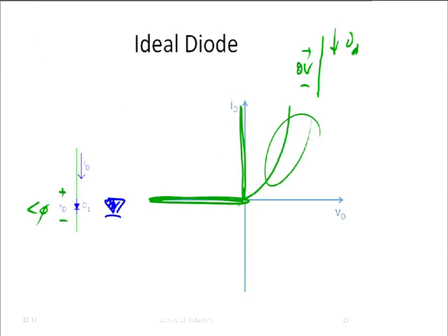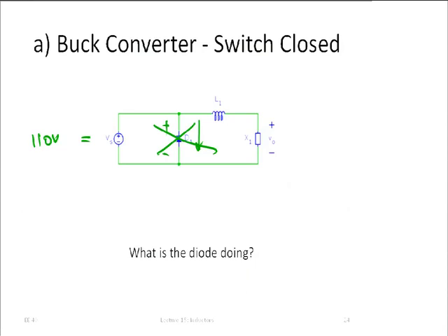Why does the current go that way? It's a passive element, so the current wants to flow in the direction of the voltage, and there's a diode there, and the diode says, stop. It's like a one-way street, right? Yeah, a check valve. Okay, so this diode's not doing anything. It's like an open circuit, so I redraw the thing, and I recommend that you redraw it also if you're in such a situation, so that's what we end up with.